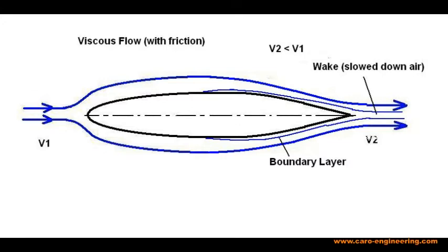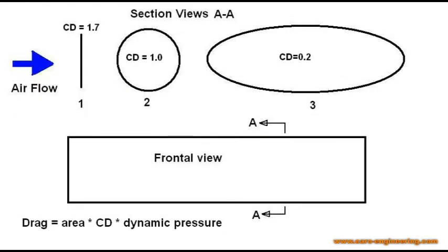There are several different types of drag, which I want to present in some detail because they require different methods to minimize them. The easiest one to understand is form drag. Every object that is moving through the air has to push that air out of the way. How much drag an object produces depends on airspeed, its cross-section, and its drag coefficient. The drag coefficient CD is a number that factors in the shape of the object because that has a big influence on how high the drag is.